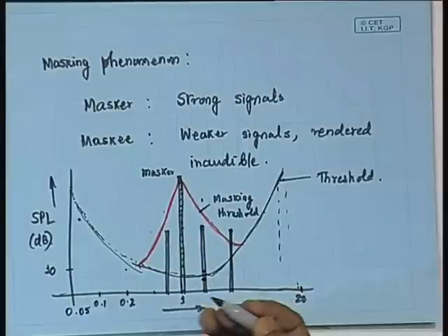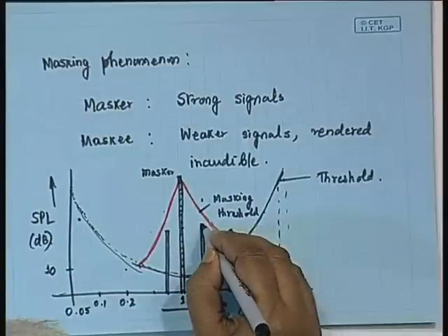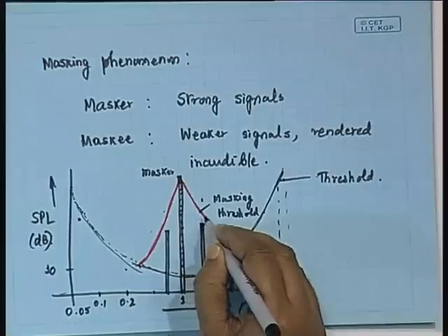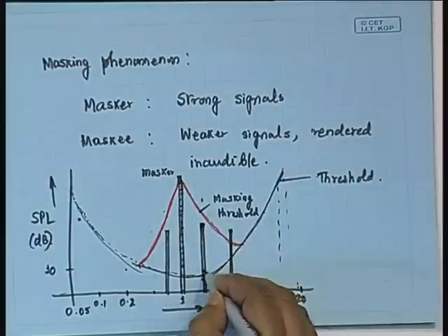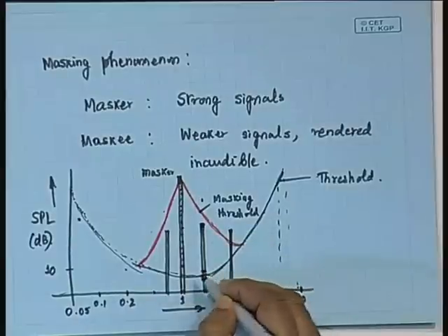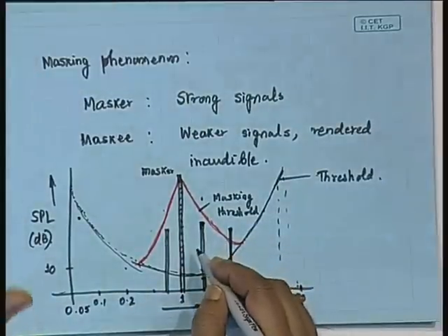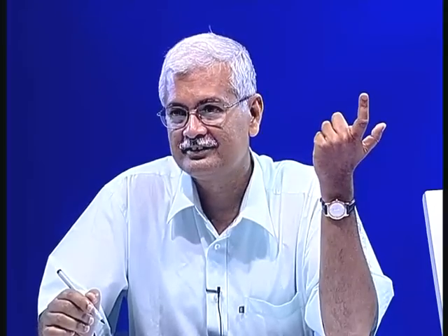What is the point? Because if a quantization noise of this much is inaudible, then why allocate more bits and waste those bits? The limiting factor is that you have to come below the masking threshold. So if there are such maskers, take the advantage of that.